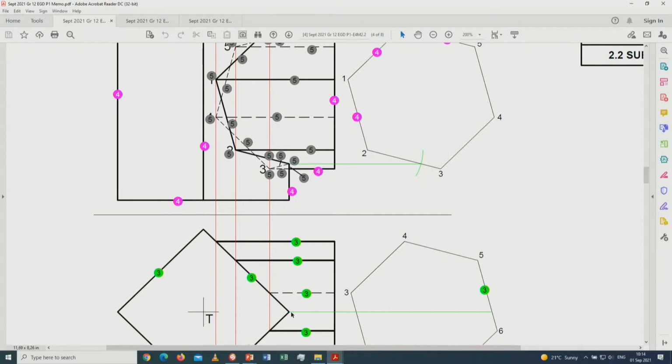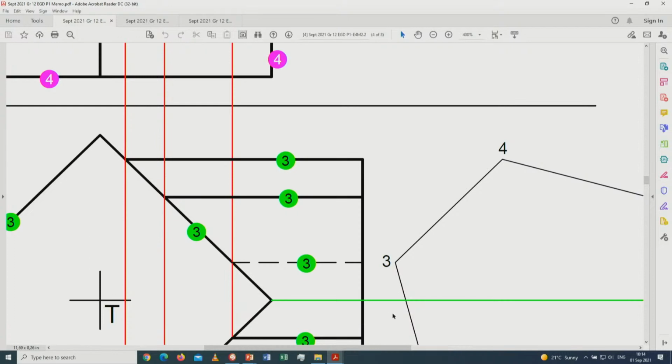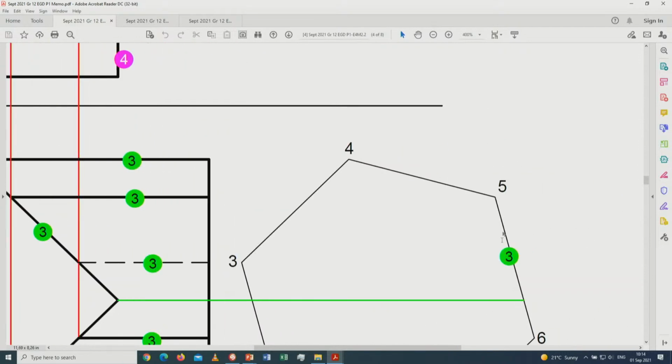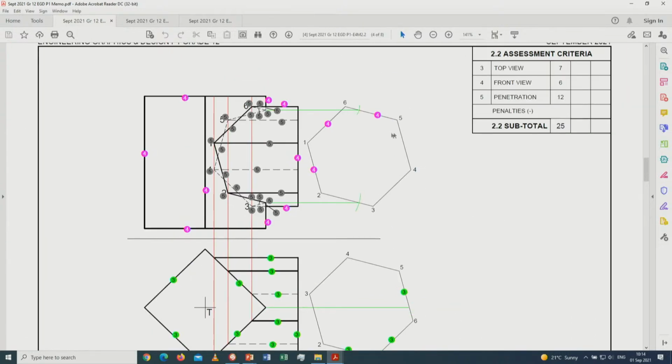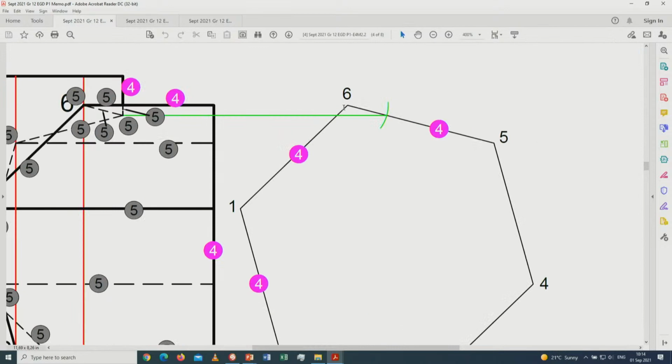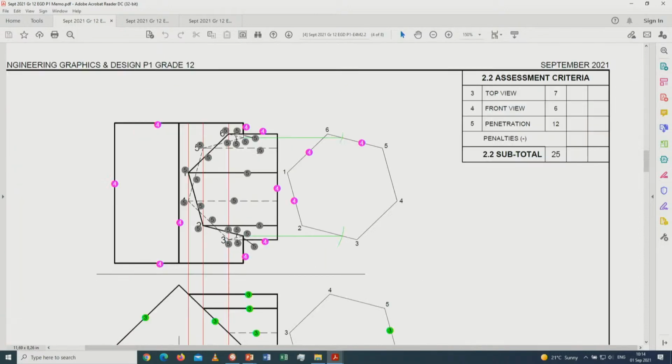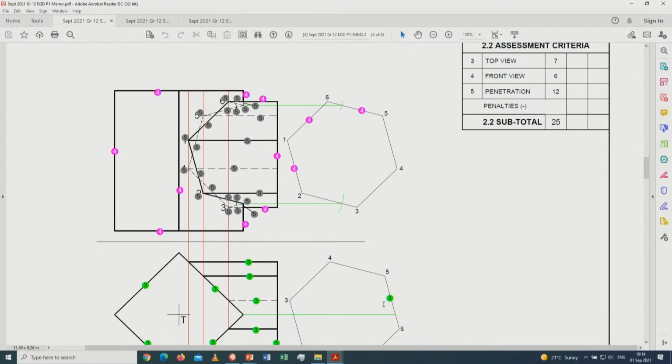There's a turn point. How far it is, if I extend this line over here on the bottom, it goes all the way up to between 5 and 6. So if I number it 3, 4, 5, that will be 5.1 towards 6. And that distance, 5 towards 6, should be measured up to this point to give you the turn point at that specific point. Like I say to you, you can also use the left view. So therefore, you don't need this view, and you don't need these construction lines.